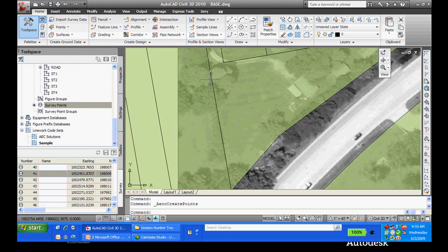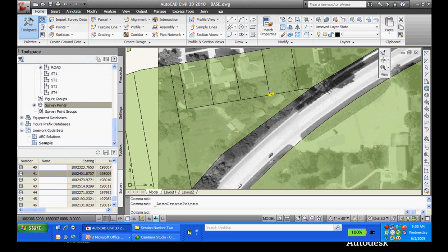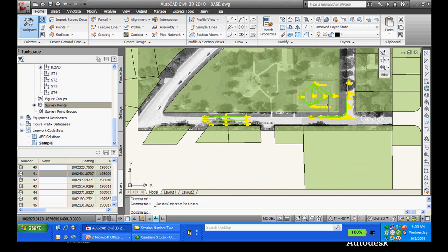Okay. Last thing I want to do on the geospatial side: I have data, I've dragged it across from geospatial, and I'm now leveraging it on the survey side. Now let's say I've collected some of my line work. Somebody down at the municipality is asking me for it, they want to show it on their GIS, and they're in a metric system. Rather than me going through and recomputing all of my stuff, I can transform it on the fly.